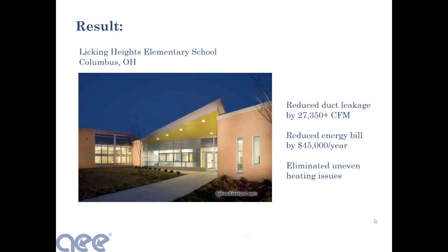So they had a contractor come in and use the aerosol duct sealant to seal up the ducts because they had a very limited period of time, just 2 weeks. The school was brand new, less than 7 years old. The last thing they wanted to do was start tearing down ceilings and walls and so on. So they were able to schedule this over a winter break. They sealed up the ductwork without disrupting any of the staff, and then they were able to get a great amount of success.